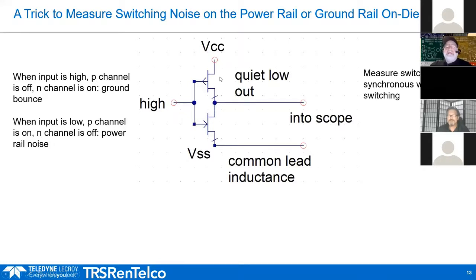And in particular, I'm going to show you a couple of examples of different systems where we can designate the IOs as either what is referred to as a quiet high or a quiet low. And all that means is the output is pegged either to the low voltage side or the high voltage side, depending on what the input is. We can do it in hardware, that's the first example, or we can do it by microcode, and that's going to be the second example I show you.